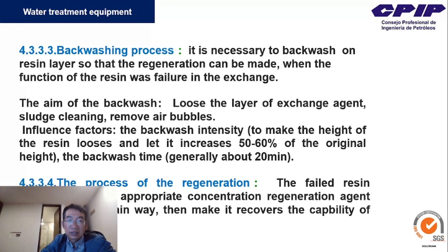Influence factors: the backwash intensity to make the resin expand by 50 to 60% of the original height. The backwash time is generally about 20 minutes.